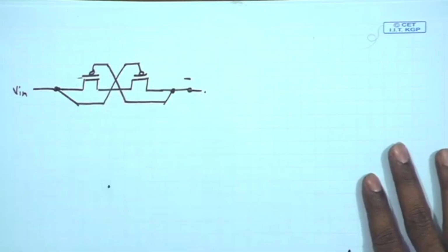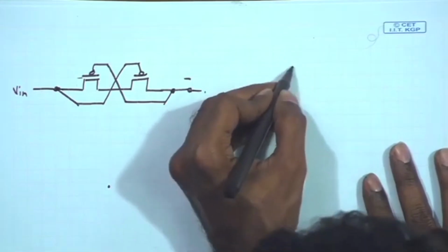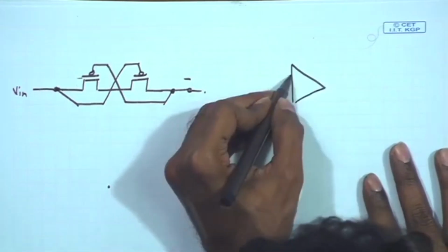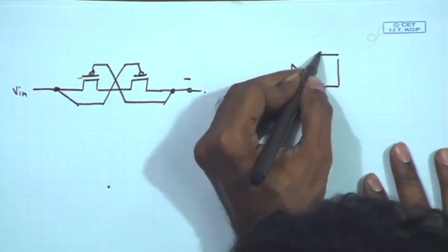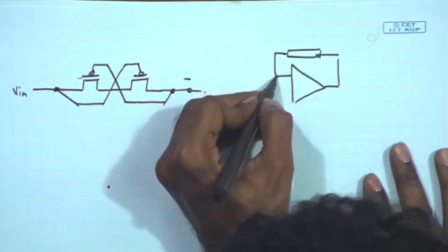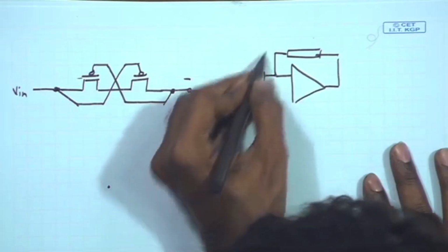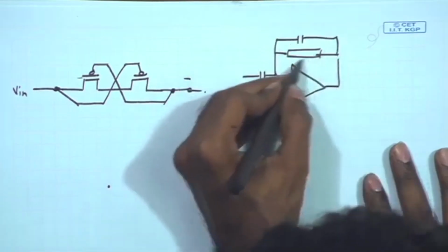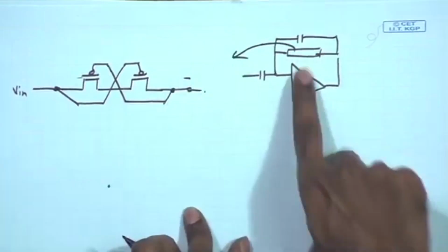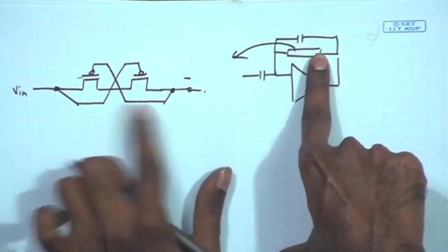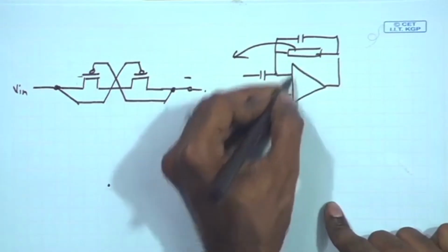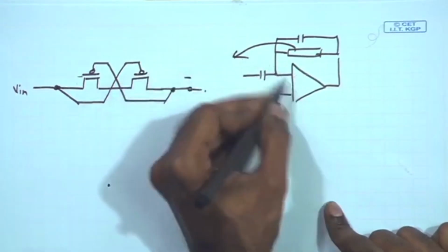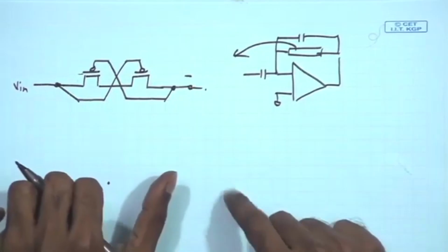Now, if you look at our negative feedback configuration, if we are having such a resistor realized between these 2 points, and of course we have this capacitor feedback. So basically we are building this large resistor using these series connected transistors, and we also need to check what the voltage conditions across these 2 terminals are going to be.